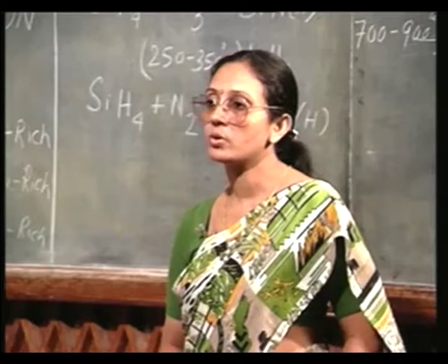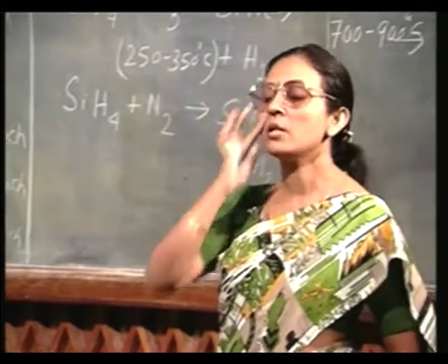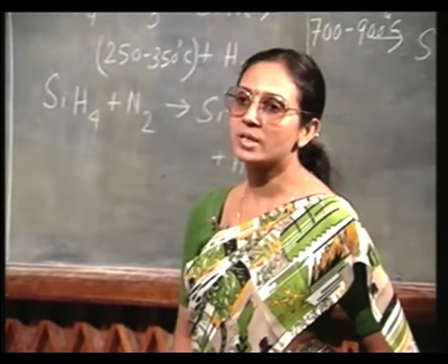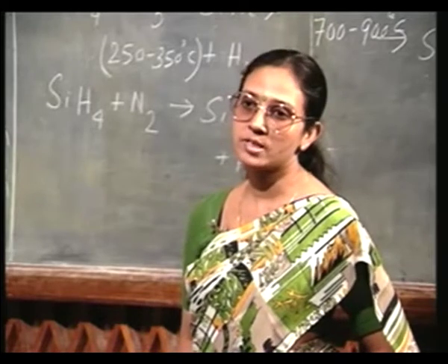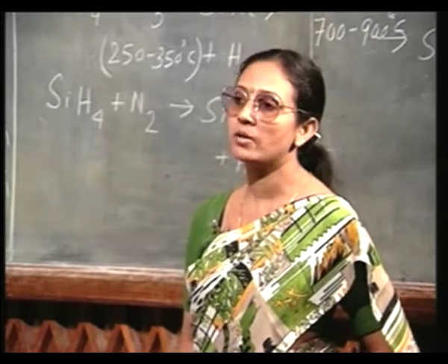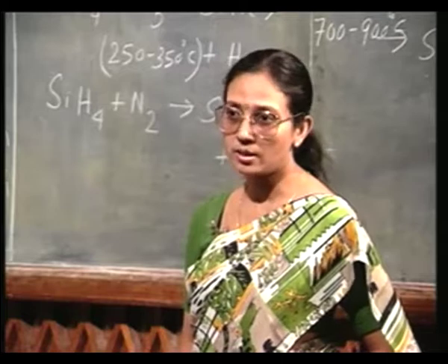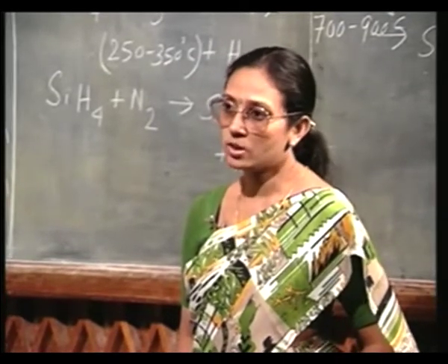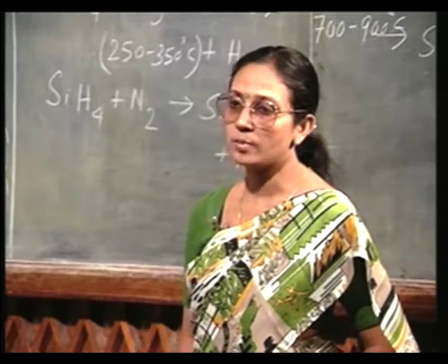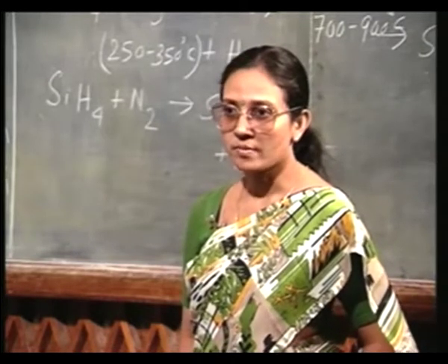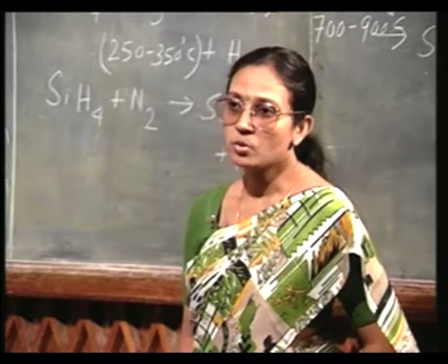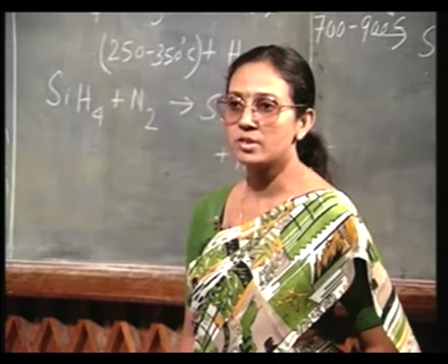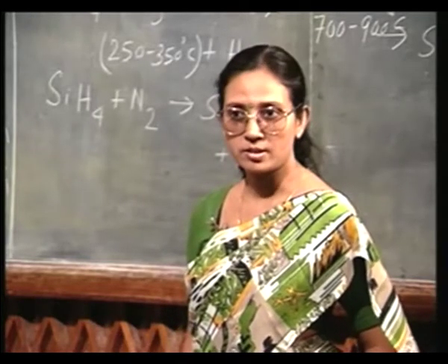Okay. So, if you want to have oxide isolation, then all you have to do is protect the active region of the substrate with a thin layer of silicon nitride, so that underneath no oxidation can take place. Now, you subject it to oxidation, oxidation will take place at the periphery and those regions will isolate the active region from the next transistor.